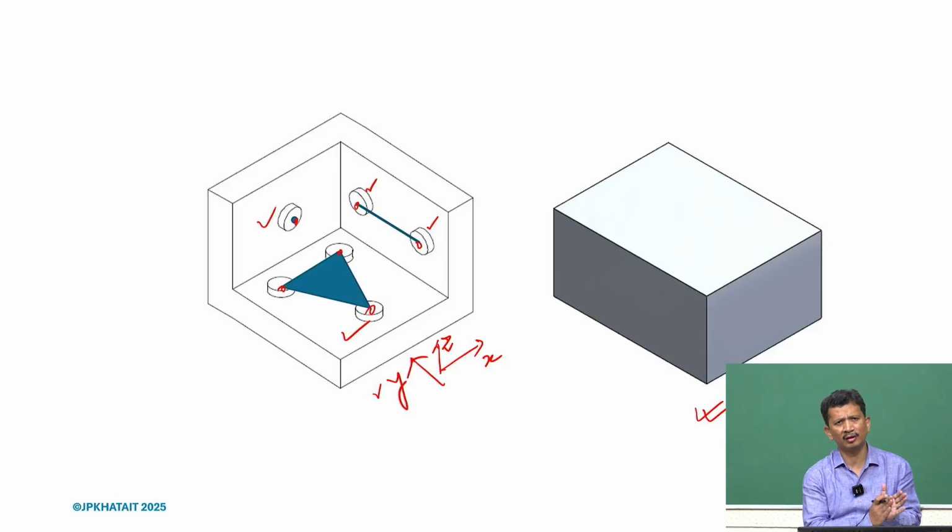So we have to understand location versus clamping. Bolts are used for clamping, to put the two parts together, but not for location. They cannot define the location properly. So we need to understand how to locate it properly so that certain objectives and specifications can be achieved.